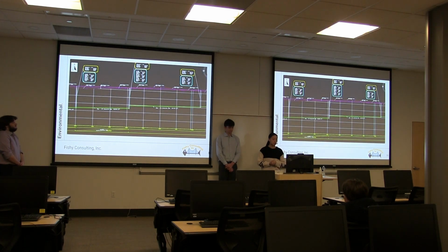And this is a sample profile view of Vale Park Road. This shows structure 40, which is that intersection. In pink is the proposed roadway, thanks to our transportation lead, and the red shows the existing ground level. In green are the pipes, and the concentric manholes are the vertical structures, as you can see there.